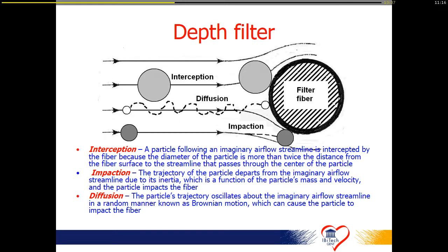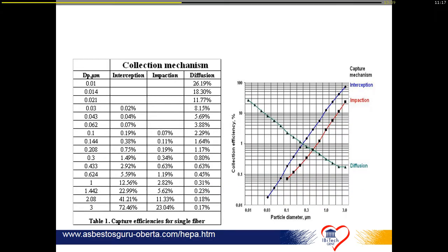Because a depth filter, and that's often forgotten, it works by interception and by captation. That means a particle, whether that would be a bubble or a particle, will actually be adhered by this fiber. And you can imagine if you increase velocity, these bubbles, because of the shear which you will actually create here, will be dislocated and will then go further through the fiber stack. And this is extremely true. As you can see here, this is the particle diameter. The larger the particle becomes, the easier it is to capture it. So again, this is in favor of probably repositioning filters when the bubbles are still bigger.